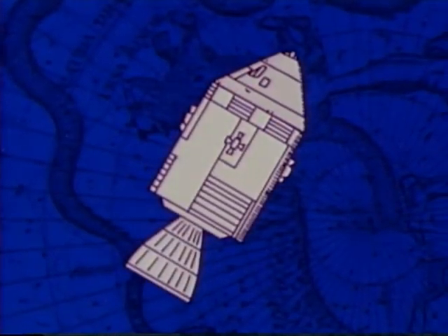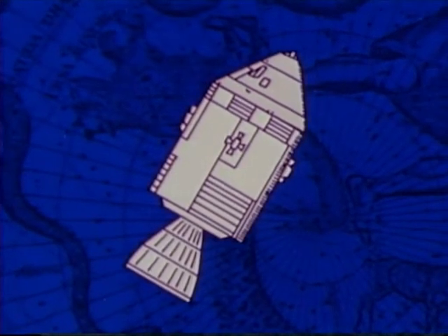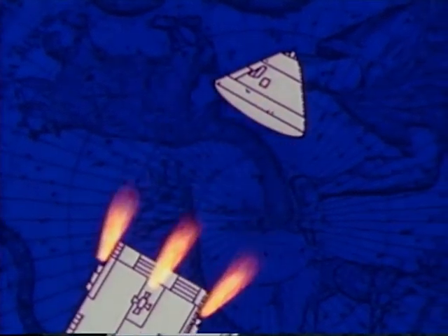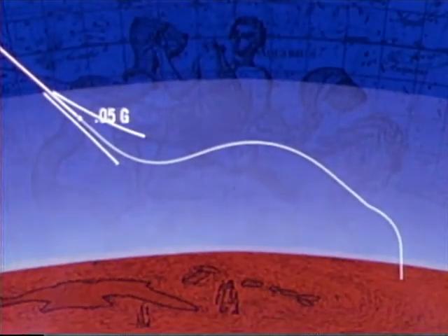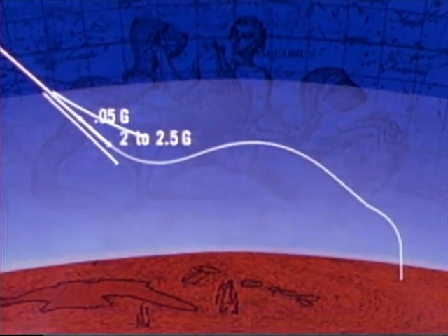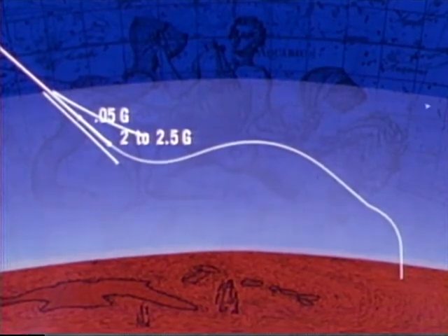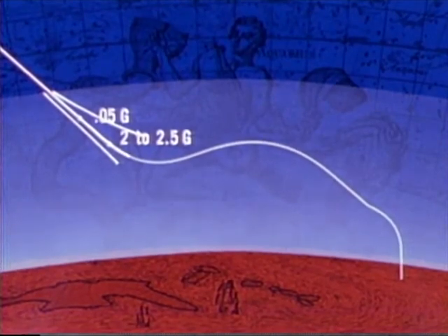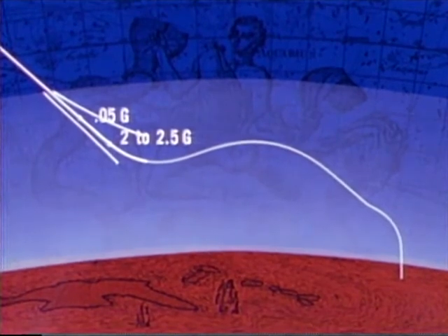Reviewing now, we see that before entering the atmosphere, the service module containing all but the entry oxygen and power supplies will be jettisoned, and the command module positioned in its trim alignment. It enters the atmosphere at the 400,000-foot level. At 0.05 G, aerodynamic stabilization begins. At the 2 to 2.5 G level, capture is considered achieved. The command module continues on the trajectory until pull-up for the controlled skip maneuver. This is where maximum G loads will be placed on the spacecraft and crew.